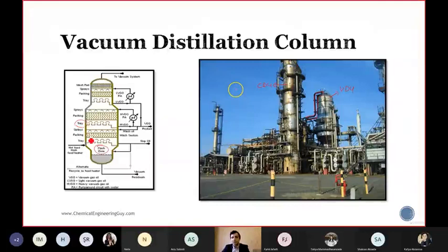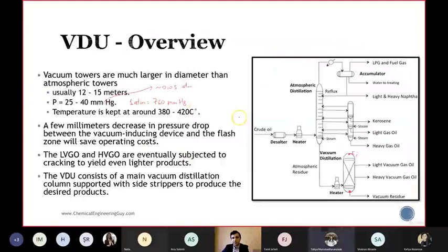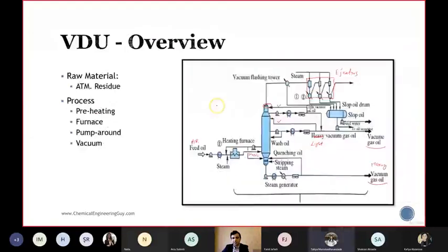So all these problems are noted, and once the plant is shut down, you check all of them in the column and see what the problem is. But if the pressure drop becomes really higher and higher, it means that you cannot operate anymore. You have to do an unplanned shutdown and see what the problem is. Okay, yes, it's clear.